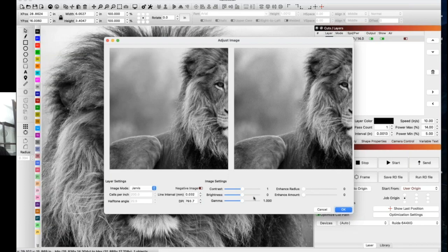The difference is huge. The further away or the closer you get, you're going from a Sharpie to a fine point pen. And the finer that dot is, the better results you're going to get, the more DPI you're going to lay down, because as you expand that beam size, obviously you're blowing away detail and you're defeating the purpose. Two huge things: the focus and your scan interval, or your scanning offset. Those have to be money if you're trying to get any type of high quality photo replication.